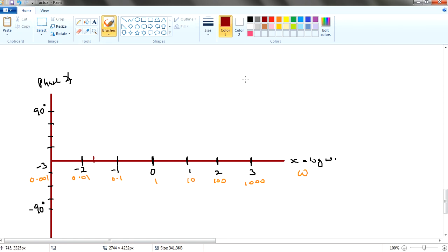Okay, what I do is that first of all, you have your omega frequency 1, right? You need to first plot out your 0.5 and 0.2 omega c and your 5 times omega c1 position. Because you are talking about the x-axis, x equals log omega. So this is the frequency, and you have to logarithm the frequency itself.